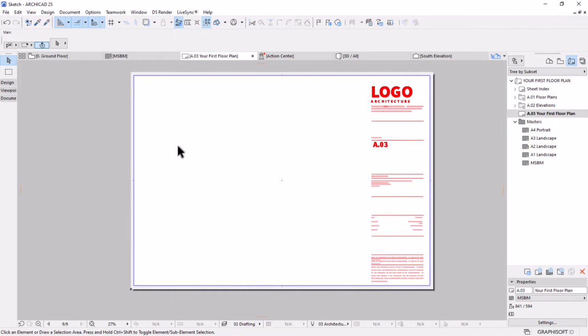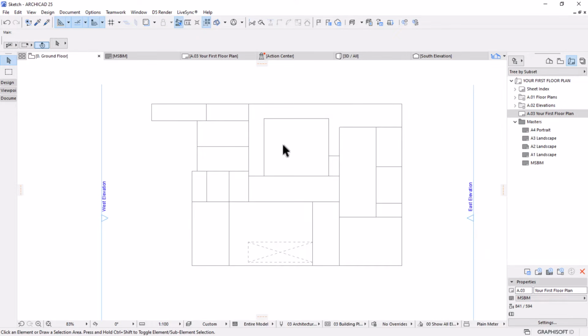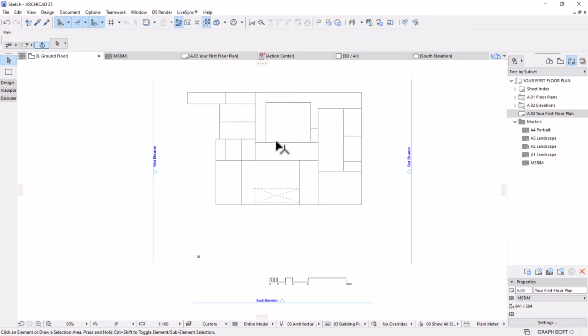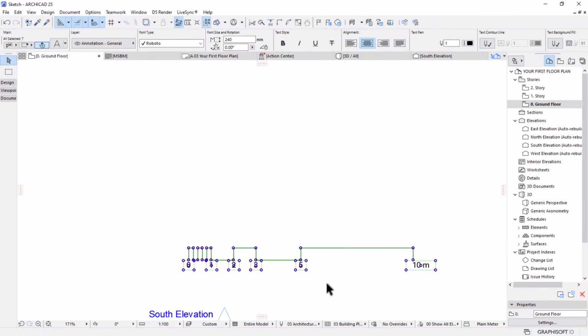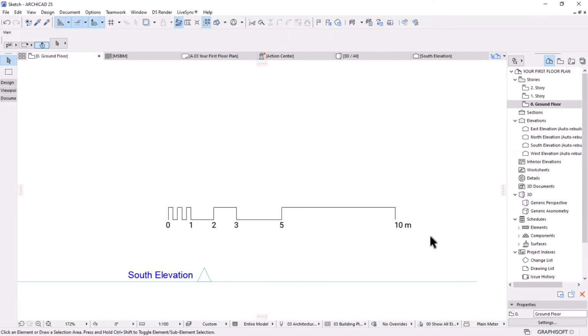To place a drawing, let's say we already have a sketch here to represent what we want. You can see I've placed the scale bar here. This is a 10 meters scale bar. If you hit M or come at the top here, there is a ruler or measure tool. The shortcut is M. If you click on it, then measure from here to there, it is 10 meters or 10,000 millimeters, because I'm using millimeters.